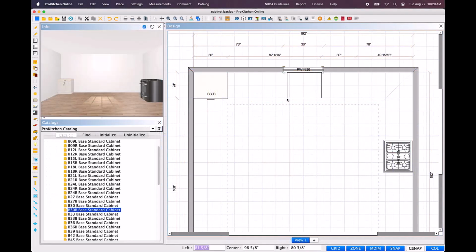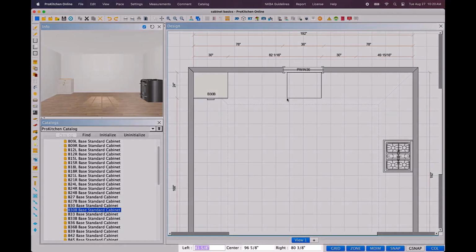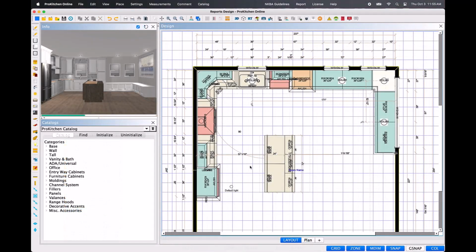If you need to move an item to its centerline placement, this may be done while initially drafting and utilizing the left, center, and right dimension fields. The last, but likely the most versatile of the dimension tools is Line to Line. This tool will provide the dimension between two lines and offers you the ability to move items into the appropriate precise location within the design.